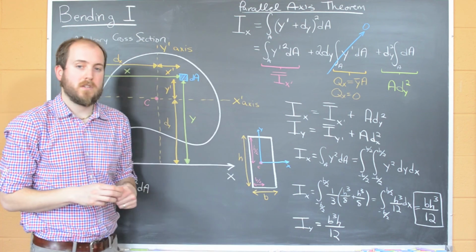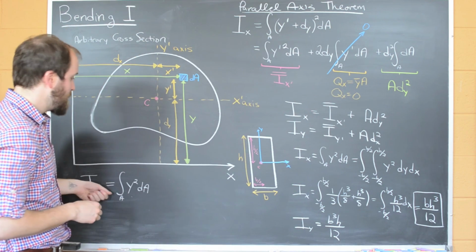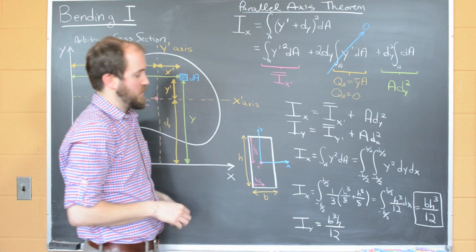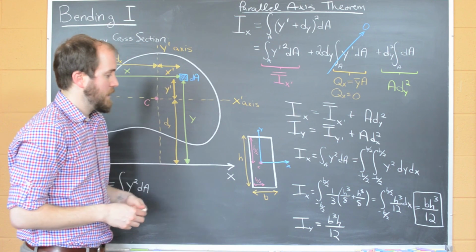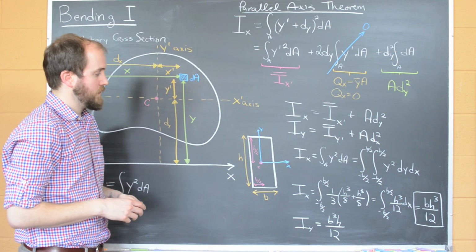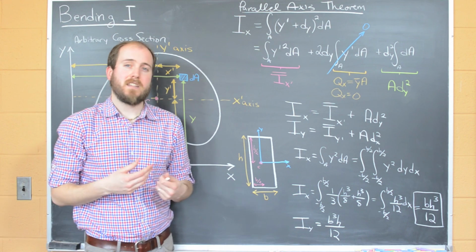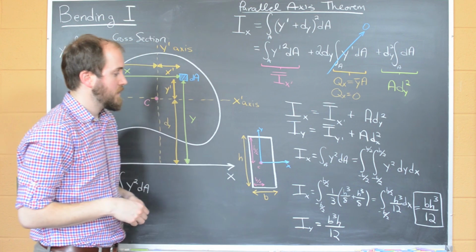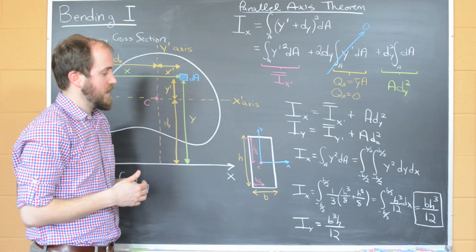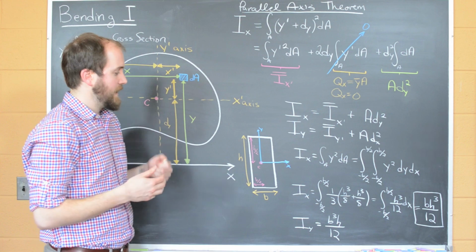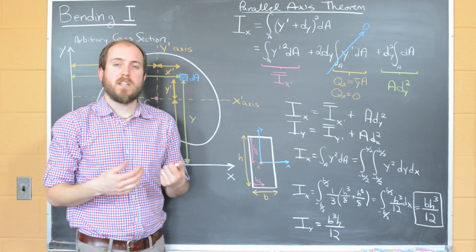So check yourself to make sure you can see how to actually implement this formula for simple geometric shapes. You should be able to do this for triangles and circles. And what we'll find out is that combining these types of shapes, rectangles, triangles, circular cross-sections, will typically allow us to get the cross-sectional area of most engineering structures.